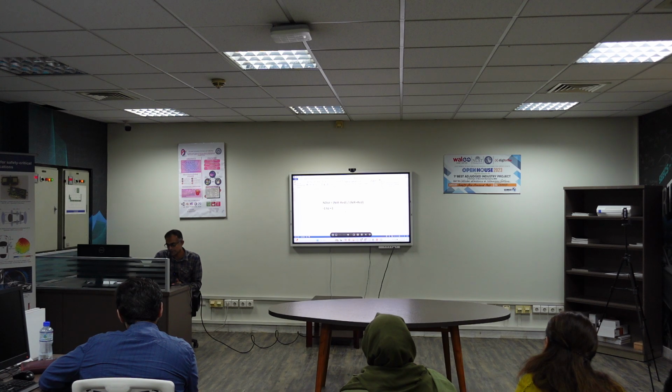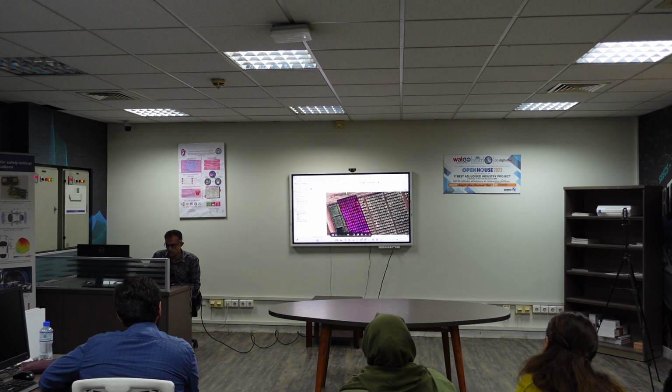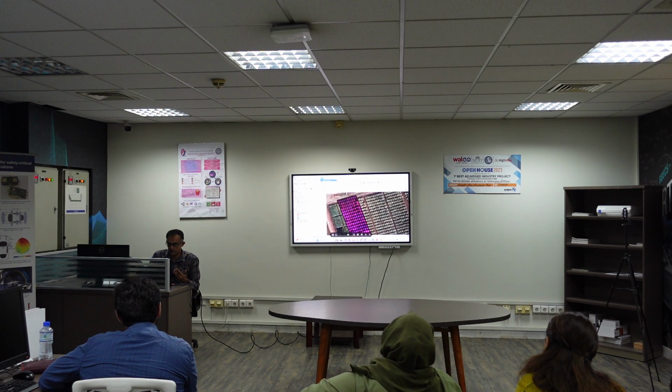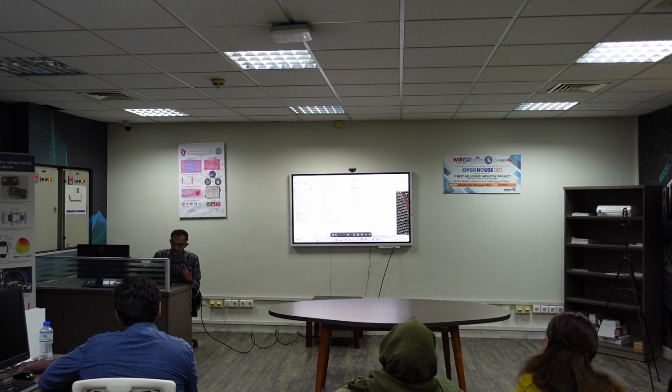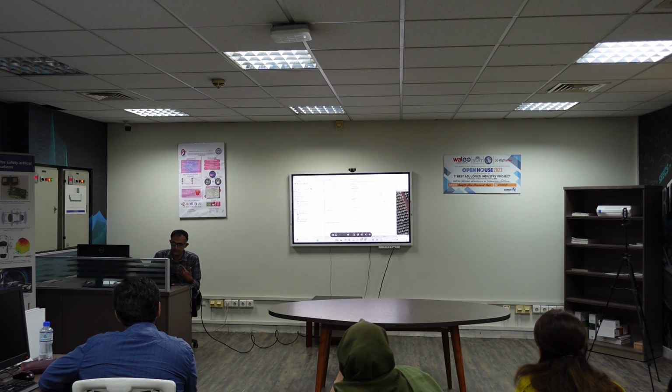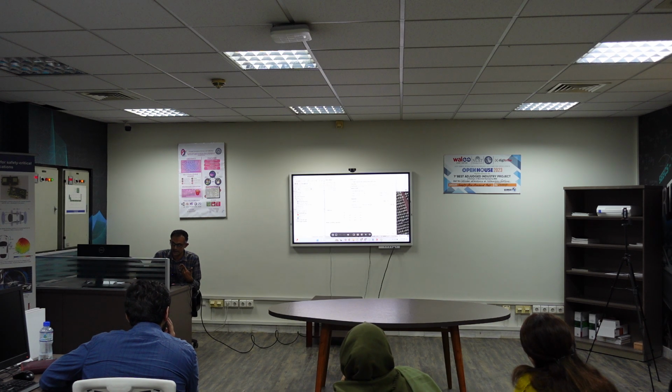So let's calculate that using QGIS. We will again go to the Raster tab, go to the raster calculator, and then again we have all the bands: red, green, blue, red edge, and NIR. So what we are required to do is NIR minus red, and so on.